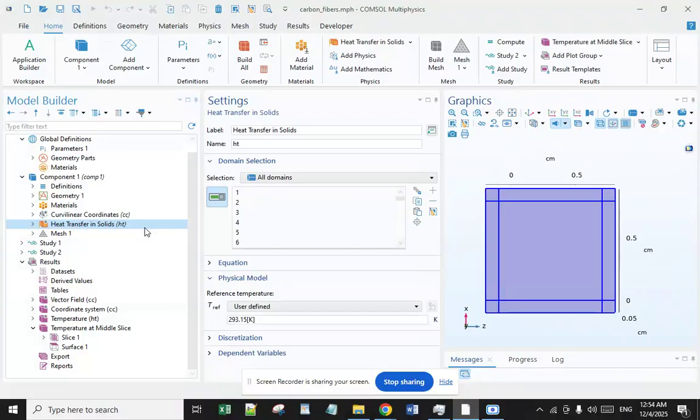According to the discretization method in this equation, the method of determining the thermal diffusivity, and hence thermal conductivity, is second order accurate with regard to the space interval between two consecutive points in each triad of points j minus 1, j and j plus 1 selected for the numerical analysis.